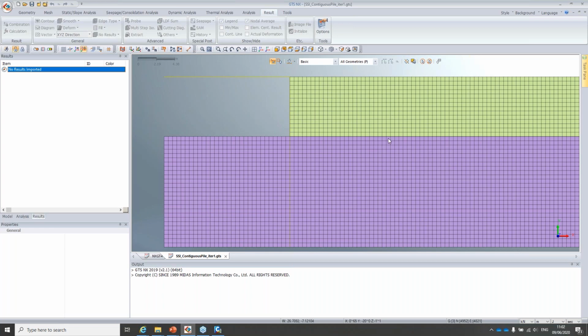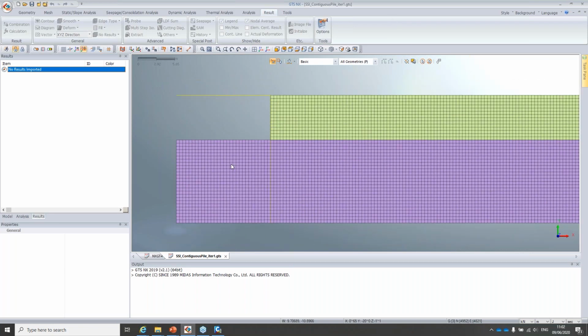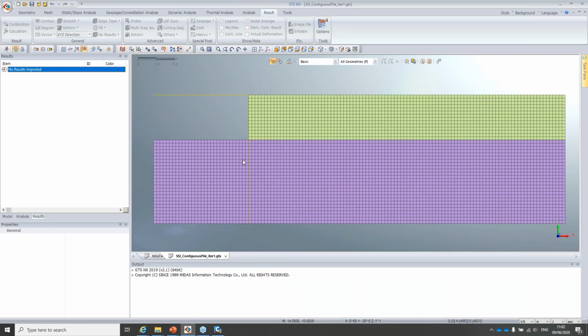That's opposite when you're comparing, for instance, retaining structures, that assuming a low value and a lower bound of this friction value is going to yield you the most onerous effects. And I think usually you need to use at least 2/3 of the internal friction angle for this interface element. We just didn't have time to cover that on this webinar.